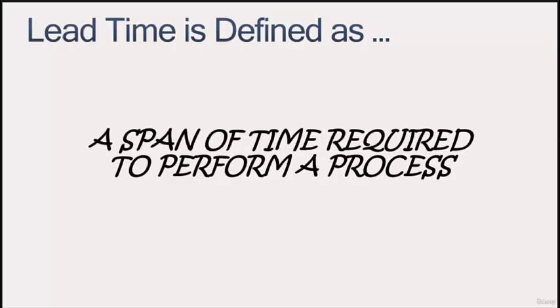Manufacturers also strive to reduce their lead times, partly to satisfy customers, but also for their own financial gain. Long lead times translate to more work in process, which is inventory of unfinished products, and can amount to a very large financial investment. The shorter the lead times, the faster the product is produced and sold and payment received in, or to pay for more materials to be bought to produce more product.